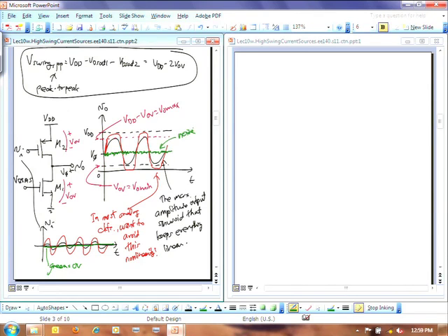Okay, that noise comes from your transistor. It can come from feed through from digital circuits that are on the same chip as your analog circuits. Wherever it comes from, it's there. It's a random signal. So pretty much random. And if your output signal after amplification is smaller than that noise, you're not going to see it. Okay, so there's where you're worried about that noise.